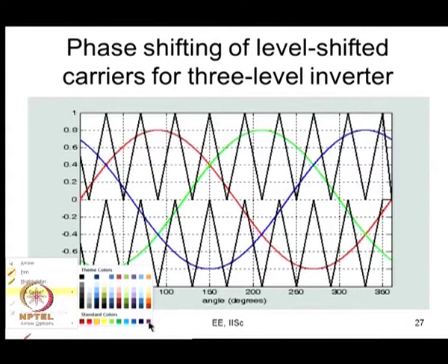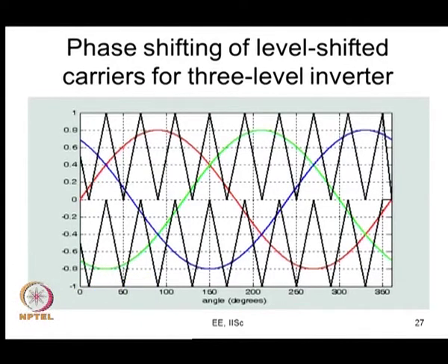let me use a different color here. Yeah. So, these are high frequency carriers, though I have shown the carrier to be a low frequency for purpose of illustration. What I can also do is I can also have this phase shifted like this. I can also have the carrier phase shifted, no problem, it will still work. The fundamental voltage I will still get. So, the 2 carriers are phase shifted from each other.